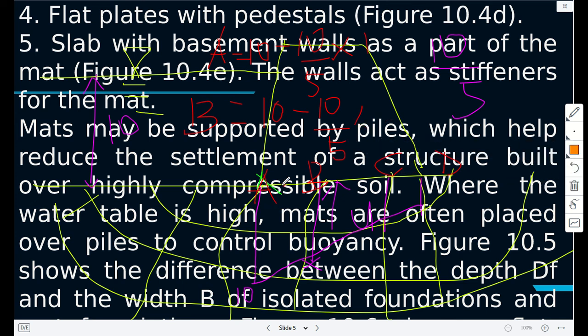If the flow net was there, this was your flow net, you use a half, so probably this is about a half, a quarter. You can estimate. So once you find the heads here, you plot as I've shown you, then you find the area and multiply by the unit weight of water, which is 9.81. That would be the uplift force, the force that the dam will experience.